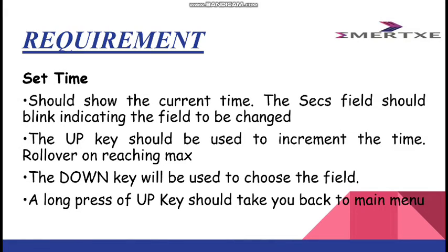Set time. Set time should show the current time. The seconds field should blink, indicating the field to be changed. The up key should be used to increment the time, with rollover on reaching max. The down key will be used to choose the field. A long press of the up key should take you back to the main menu.